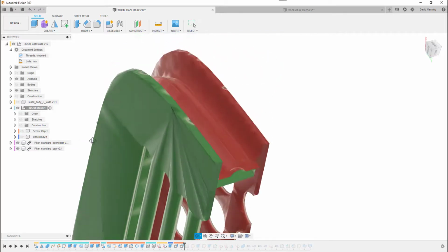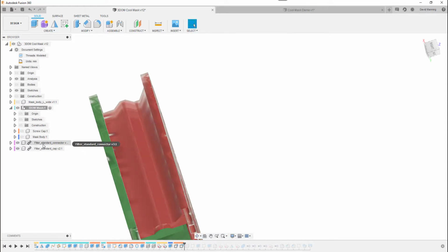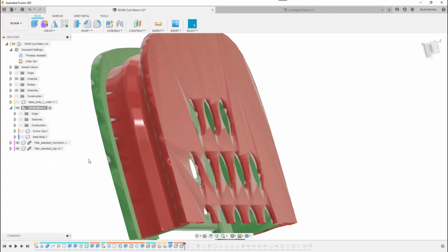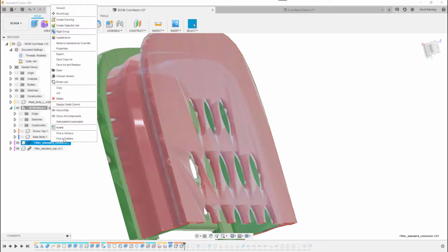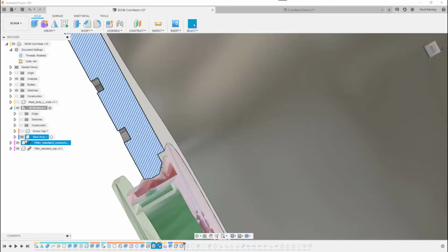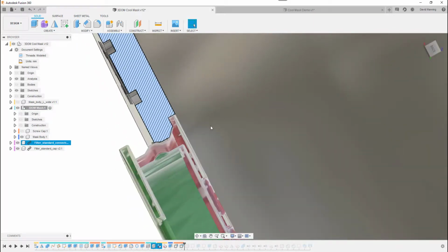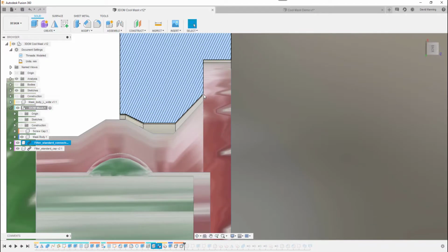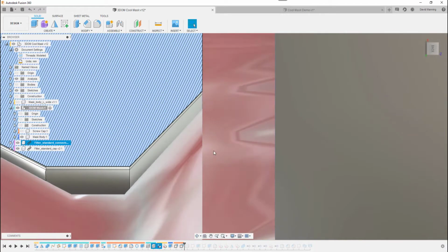I wanted to make sure they fitted properly, so I've simply inserted them as new components. That allows me to do joints. Not that I have worried about it in this case. I just wanted to position them, and I've just done that manually to check that they fit. Now that's just simply inserting the mesh and then using that move command to position them. Having it sectioned like this makes it nice. I can make sure I get that square surface there, and I just move it back and forth until it fits. You can see there, I've probably gone a touch too far.